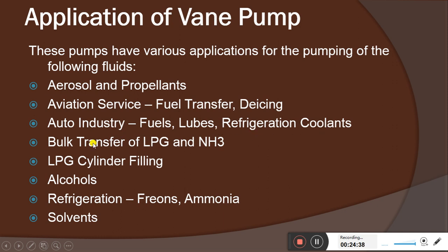Bulk transfer of LPG and NH3, LPG cylinder filling, and alcohol industries can use this type of pump. Refrigeration, freons, and ammonia can be pumped, and solvents. So these are the fluids that can be pumped using vane pumps.